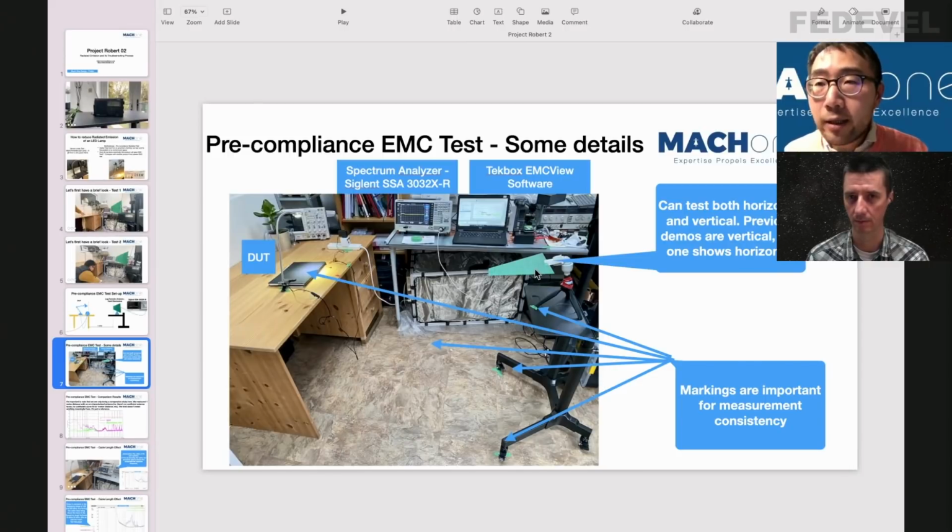Exactly. Normally, different antennas will have different signal reception ranges. For example, this antenna is supposed to have very good reception between 400 megahertz and 1 gigahertz. But as you can see later on, for this noise, which is predominantly between 10 megahertz and 300 megahertz, this antenna still can receive the signals. So the point is, if you have any sort of antenna, even a TV antenna, you pick up the noise, and then you make some change and see a 10 dB, 20 dB reduction, then you know you have reduced the noise.